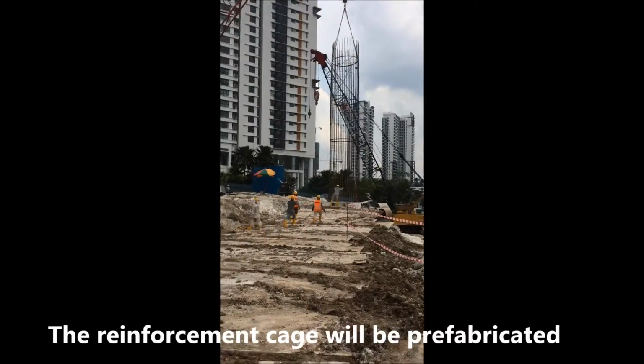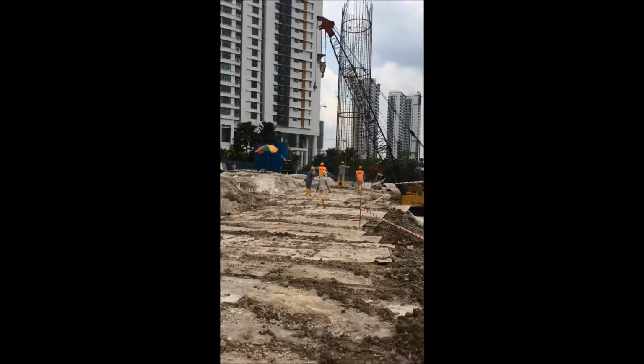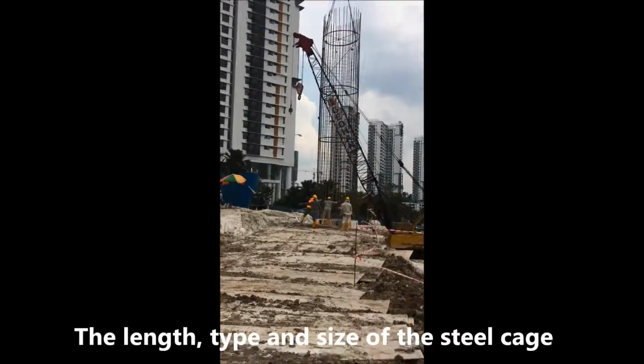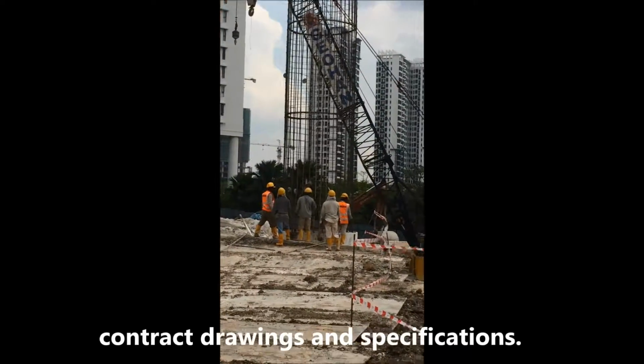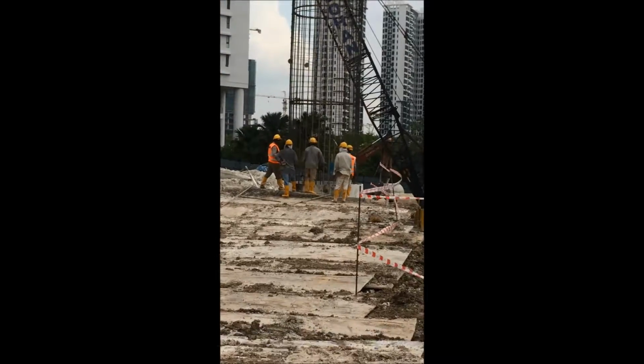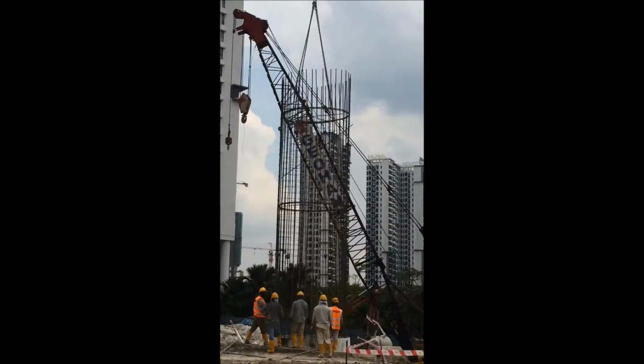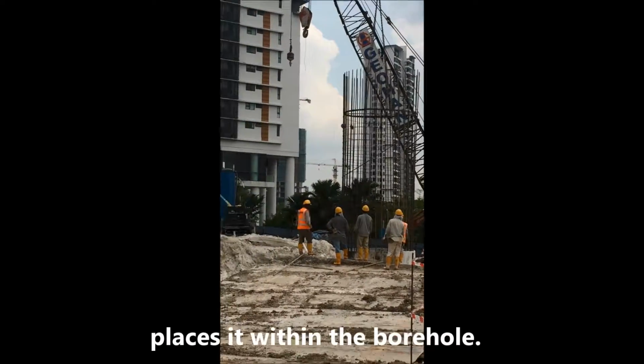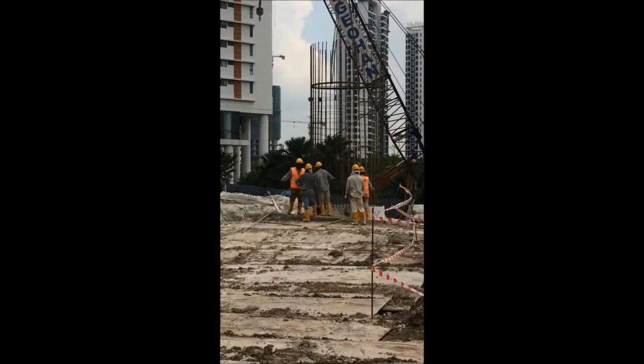The reinforcement cage will be prefabricated. The length, type, and size of the steel cage will be according to contract drawings and specifications. The steel cage will be lifted up using a service crane and placed within the bore hole.